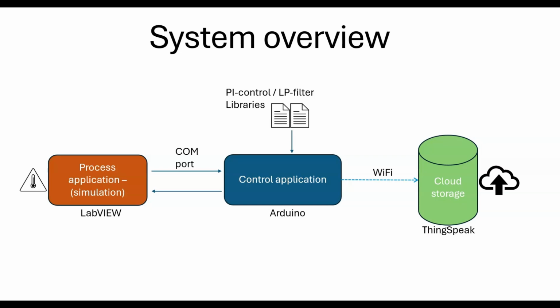The Arduino has two-way communication with a LabVIEW application through USB, which is run on a separate computer. The Arduino is connected to a Wi-Fi hotspot and uploads data to the cloud storage. Two libraries have been developed in order to give the control application a better structure.